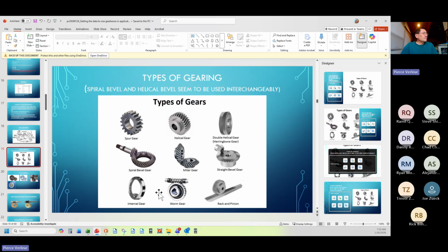Down here, we have a complete departure from these types of gears called the worm gear. And a further refinement of the worm gear is the double enveloping worm, which I'll show you in a second. This geometry, in my humble opinion, is unsuitable for precision applications. It has way too many limitations and doesn't have the significant cost advantage that it used to have.